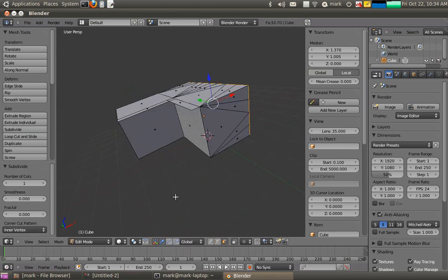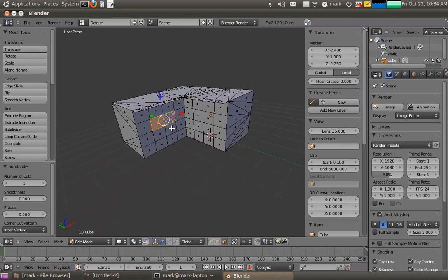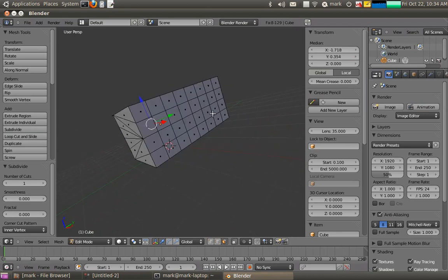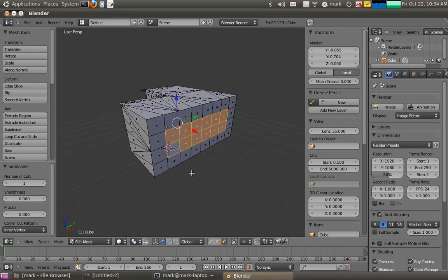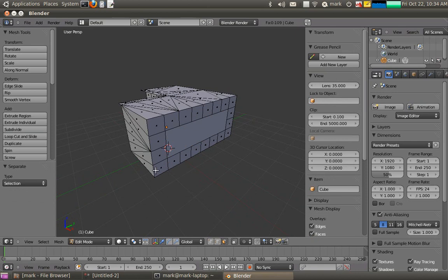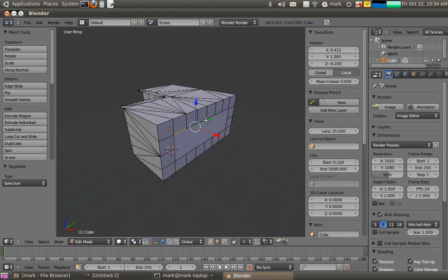So I'm going to add some windows into these areas, and I'm just doing some shortcuts here to make these faces here windows. And the way I'll make them windows, as you'll see in later tutorials, they need to be separate objects in Blender in order to be able to actually assign hierarchical data structures and whatnot. So there we go, separate windows. Now what I might just do is add some eaves over this southern window.